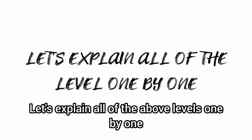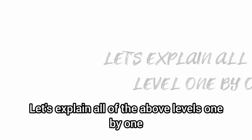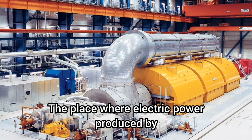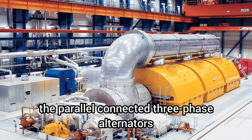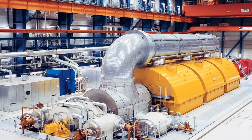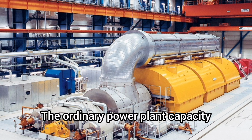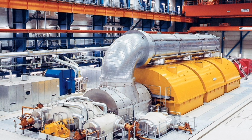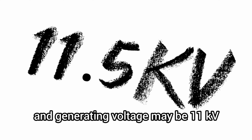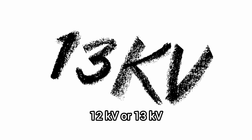Let's explain all of the above levels one by one. Generation, or generating station. The place where electric power is produced by the parallel connected 3-phase alternators/generators is called a generating station, i.e. power plant. The ordinary power plant capacity and generating voltage may be 11 kV, 11.5 kV, 12 kV, or 13 kV.